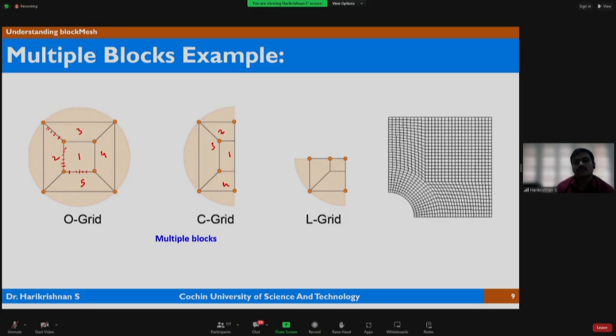And the last one is known as L grid. So when we have 1/4 one, the right hand side figure, the final mesh you can see here, is taken from a tutorial called plate hole tutorial, which is already available in OpenFOAM. So you can see it's a combination of a 1/4 of the circle followed by a rectangular block. So here we have a semicircle, 1/4 of the circle, and a hollow circle, you can say, right? It's not even a complete circle.